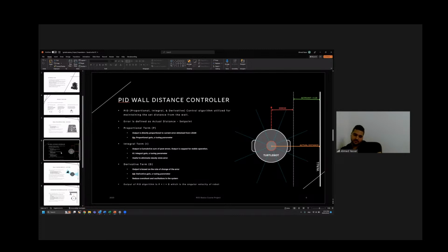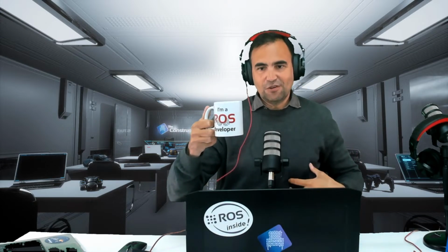TF is a complex concept to understand, and it's key in ROS specifically and in robotics in general. It's about the different frames and how to move between them inside a single robot. For example, the head has a camera and is detecting a mark. The mark is, I don't know, 1 meter from the camera, from the head, not from the center of the robot, not from the hand. So you have to convert that to the hand, so the robot knows how far it is from the hand itself.